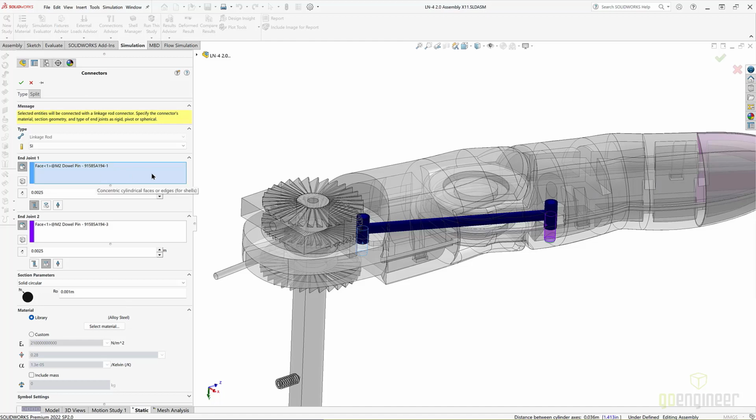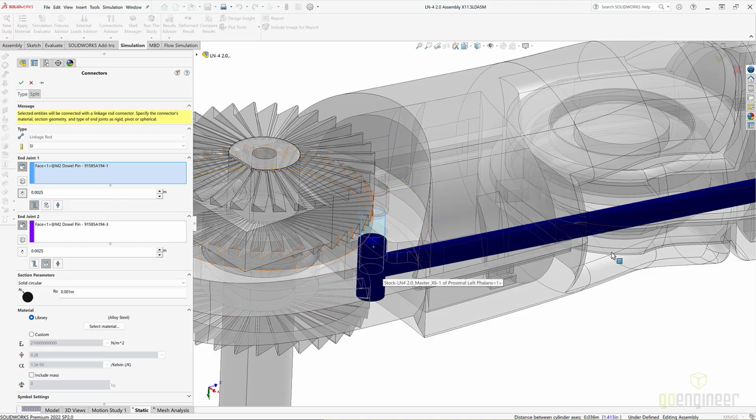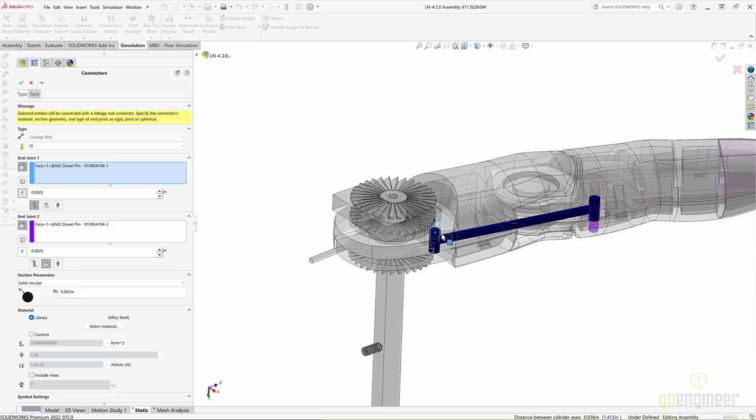So I selected that first face of that pin, and when you make it, there are offsets that you can apply to this. I'm going to be going into the offset right here. So I have it upwards from the center point of that pin. It's going up 2 millimeters. And if we need to go down, there is a reverse direction. I'm sure many of you designers know the reverse direction. It's a very easy thing to just say, hey, flip this between here and here. Flip it right down. So you can do diagonal connections. You can also just offset it to whatever makes sense. As long as you know how to represent this physically, that's when I would use the virtual connector.